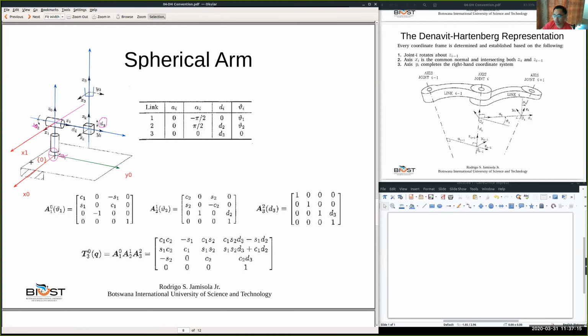We follow what the author is doing, and so by saying that X1 is here, then we know already where the origin of frame 1 is. We draw it, and you see it in the pink. That's the origin of frame 1 because that is where X1 and Z1 intersect. So now we know that is the origin of frame 1.